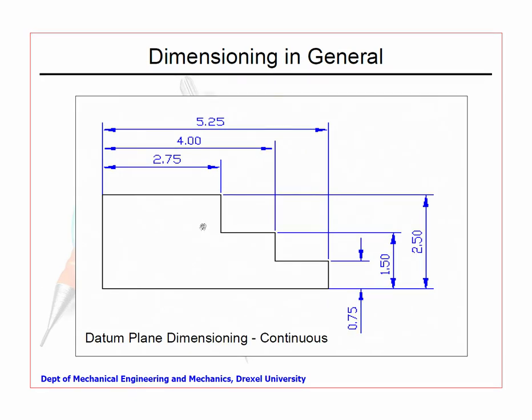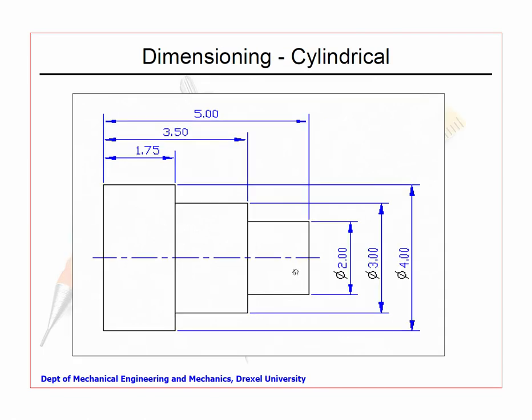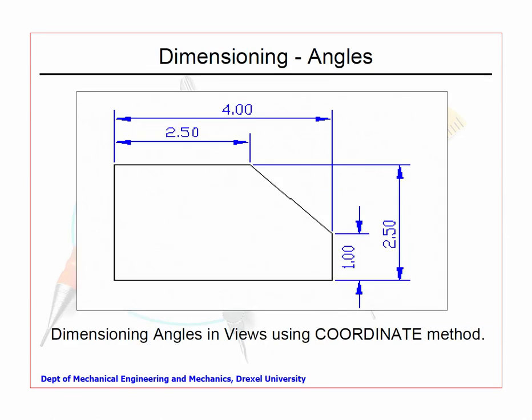While this could be a section view, half section view and all this, invariably these cylindrical parts are all mentioned with the diameter symbol. Only in rare cases the word dia is written, otherwise depending on the precision you require, 2 digits are shown there. This looks like auto generated in some CAD package, since it is mentioned it is AutoCAD in the beginning, probably it is done like this.